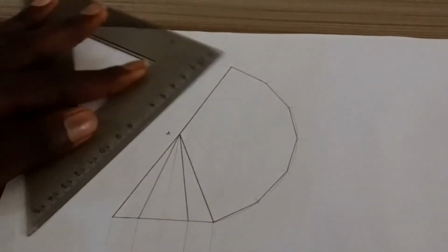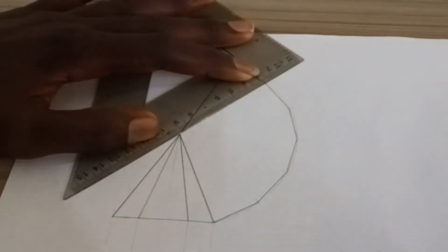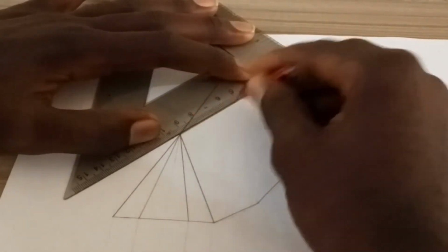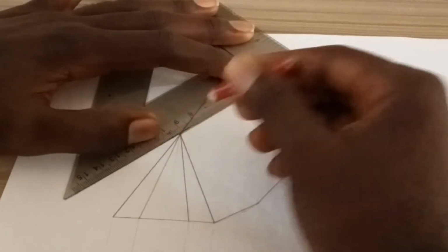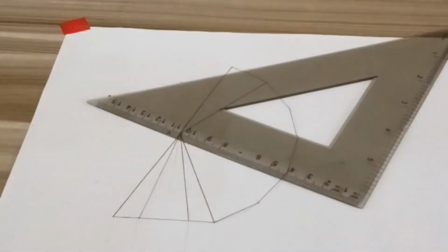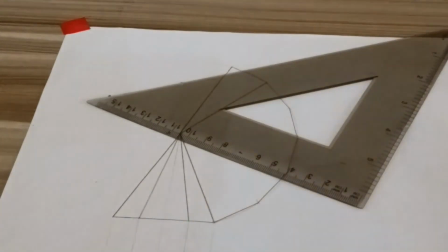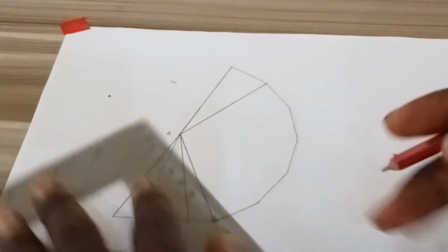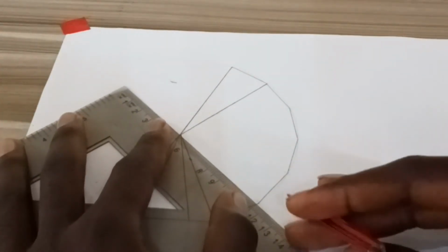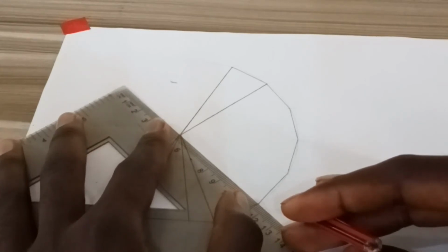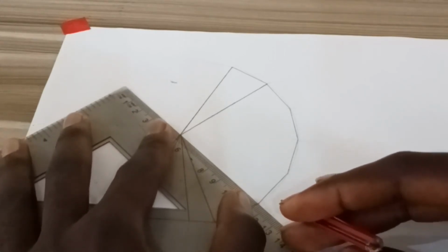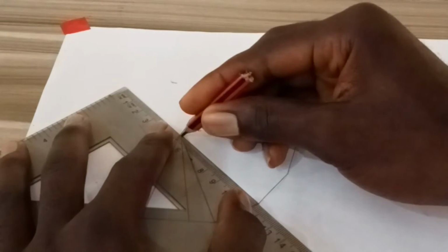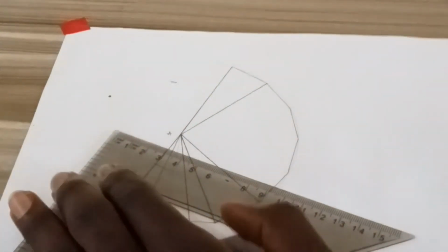Hope I got my numbering right for the arcs, so I think it should be about 6 if I didn't count wrongly. So join the apex of the triangle to the last arc. You do the same for every single arc you've drawn. So the penultimate arc, you join to the apex of the triangle, which is your front elevation, and you do that till you go around the semicircle again with thick continuous lines, because this is our development. This is how the development of a hexagonal pyramid looks like.